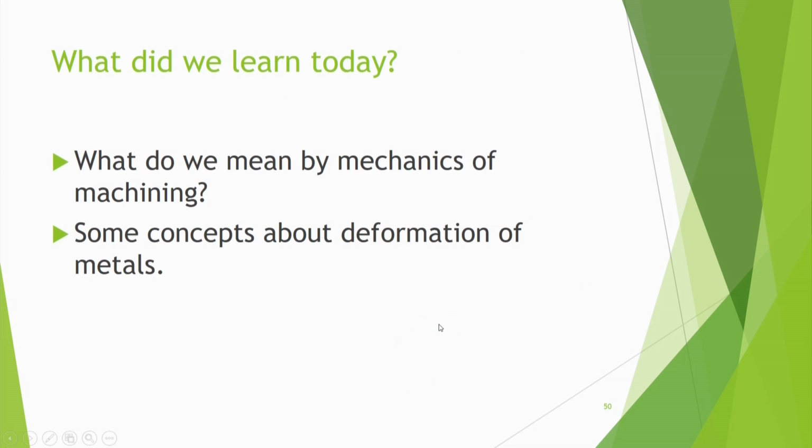So, dislocation phenomena is actually responsible for causing the plastic deformation, but we will also study phenomenological models which are developed based on physical observations. They do not see what is happening inside the material, but they are very useful. For example, your von Mises criteria or Tresca criteria, how the material is yielding, these can be called phenomenological material models. So, what did we learn here?